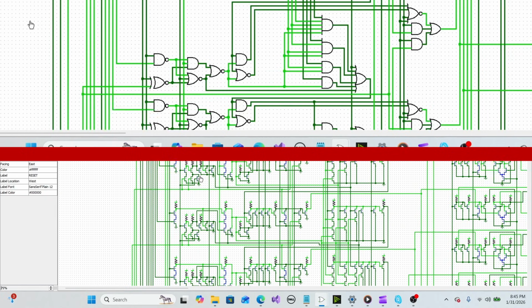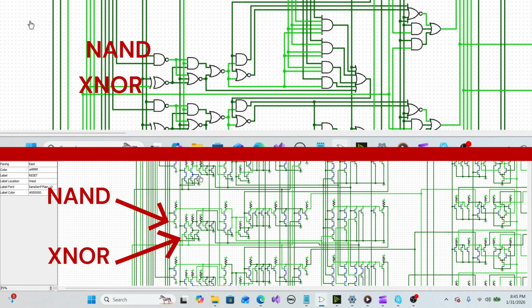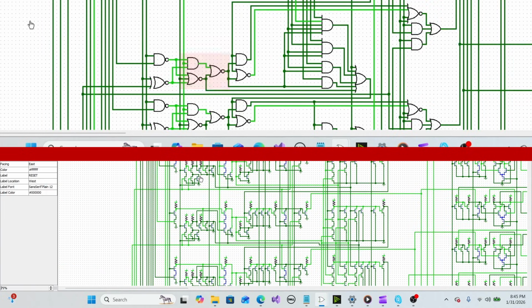We can see the NAND and XNOR gates that are responsible for enabling the A operand and inverting the B operand, respectively. We can also see the Chameleon gate, which is responsible for both selecting and performing a given ALU operation. The only difference here is I changed the AND gate to a NAND gate, and I changed the NOR gate into an OR gate, which allowed me to change the final NOR into an AND. This allowed me to simply connect the outputs of the two gates together instead of explicitly building the final AND gate, which saved me a lot of transistors.